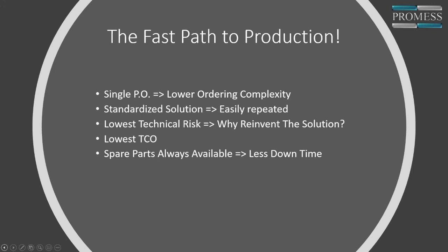Yeah, I'll elaborate a little bit more on that. We do interface with PLCs, so our controller has fieldbus options available on it, like Profinet, Ethernet IP, Modbus TCP, and things like that. So if there are other machine functions that you still want the PLC to control, we interface that way.